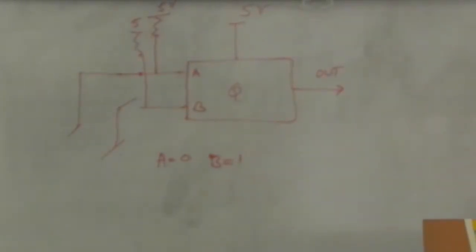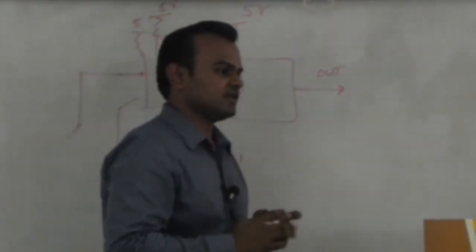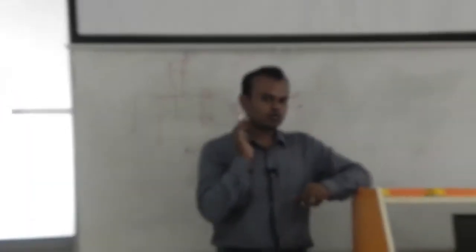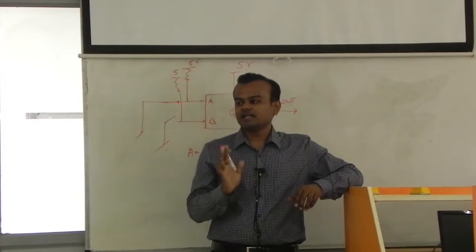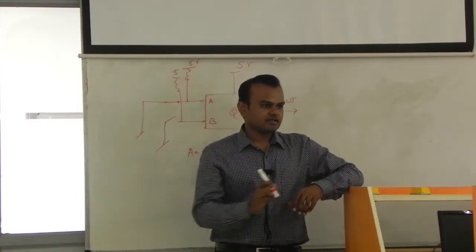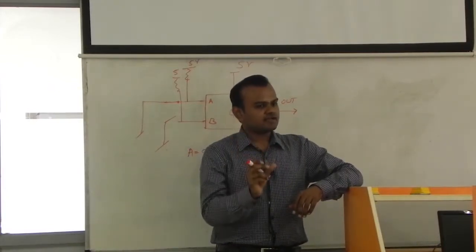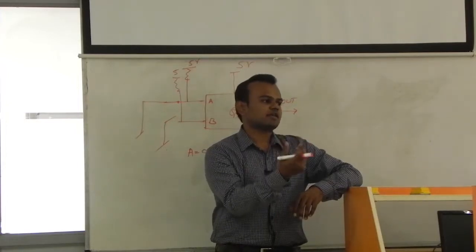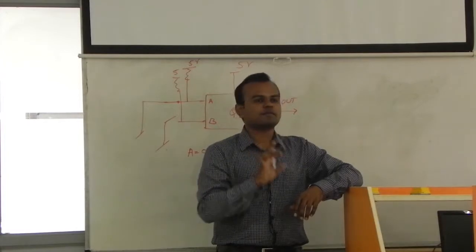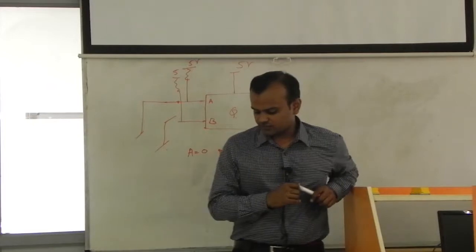Now in microcontrollers, each and every GPIO has a pull up and pull down resistor system. When a GPIO is configured as an input, to prevent any unintended triggering of the logic from the voltage levels on that particular pin, these pull up and pull down resistors are used. There are simple registers in which you can load the values, and the microcontroller itself will enable or disable the pull up and pull down resistors. When you use it as an input, this is very useful.